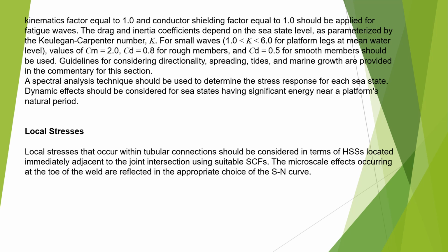Local stresses. Local stresses that occur within the tubular connections should be considered in terms of hotspot stresses located immediately adjacent to the intersection using suitable SCFs. The microscale effects occurring at the toe of the weld are reflected in the appropriate choice of S-N curve.